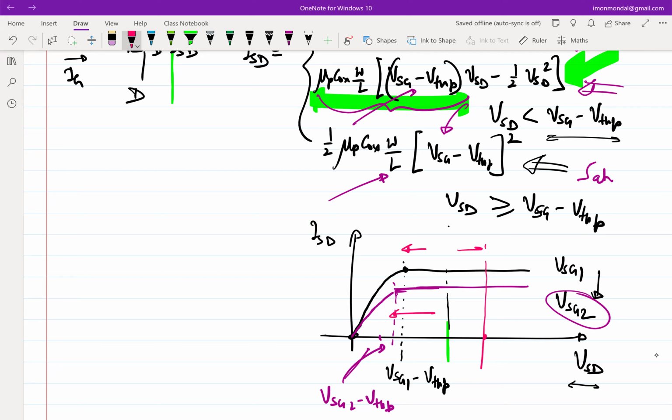It's not as if you would like to have an amplifier which operates only at one very sweet biasing point, and you change the operating point slightly and everything goes for a toss. That's not a good design, right? So ultimately, a good design should allow for a range of variations. So in certain ways, the choice of your operating point is also kind of deciding how much variation you can tolerate. Okay.